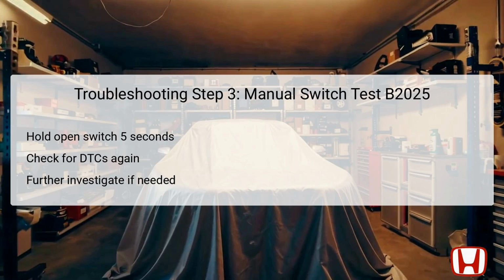After this duration, check the HDS again for DTCs. If B2025 is still indicated, it's clear that the problem persists and warrants further diagnostic steps. On the other hand, if the code does not show up, it suggests that the system may be functioning intermittently, potentially pointing to poor connections that need inspection.